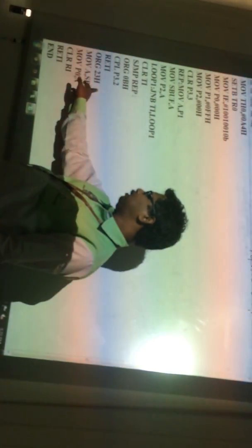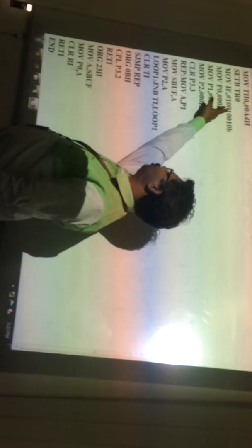So main program, then ORG 23H. In that we are going to have serial communication, the serial interrupt. SBUF is moved to A. A is being loaded to P0. Clearing the RI. Returning to the main program. End. Okay. So therefore we have enabled both the timer interrupt and the serial interrupt. Now we can execute this program.